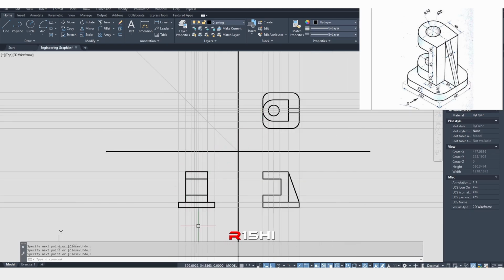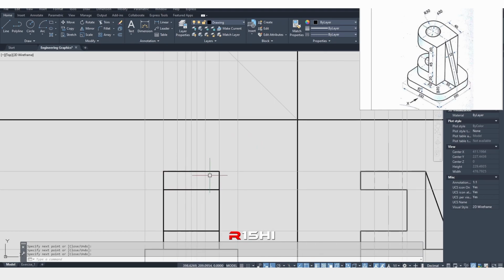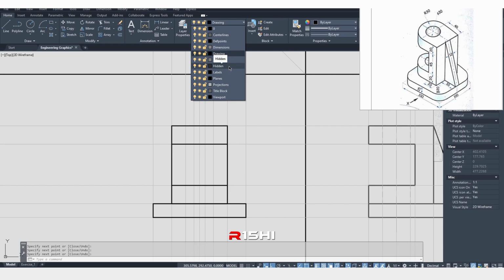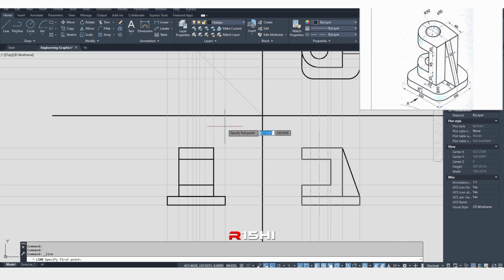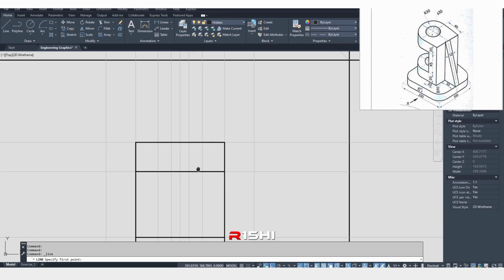the outlines. Now these holes will be visible as hidden lines over here for us. We will be representing them as the hidden geometry. So we'll go to hidden line there. Go to line command. You know the diameter one coming over here. So these are the ones.